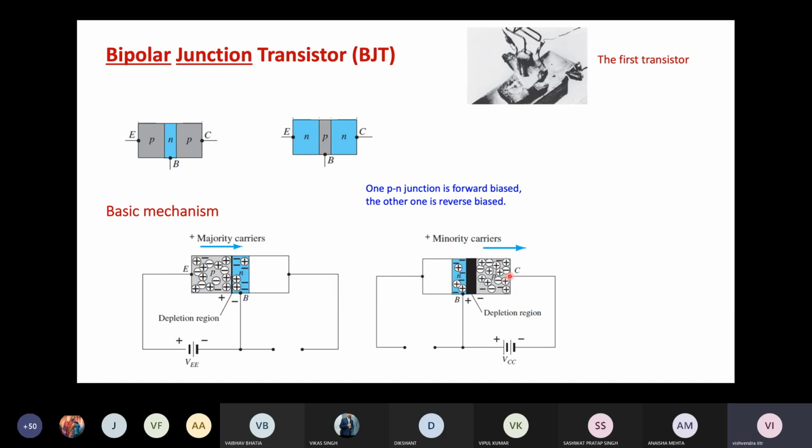Similarly, a voltage source is only connected to the collector terminal, and base is sometimes grounded or maybe connected to the other circuit. So in that case, this VEB will be confusing because it might not be connected to the base terminal. It might happen that base is grounded and the battery is only connected to the emitter terminal. And this is also the convention in MOSFETs actually.